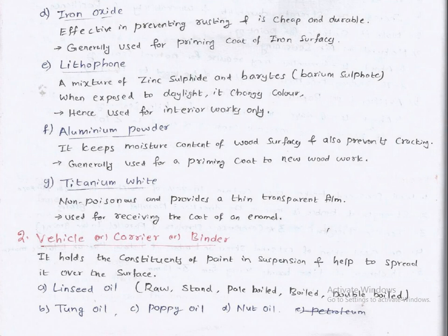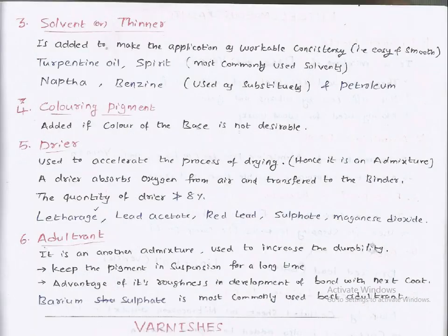Solvent or thinner. It is added to make the application workable, consistent, easy and smooth. Turpentine oil, spirit, most commonly used solvent. Naphtha, benzene, used as substitutes, and petroleum. Colored pigments, added if color of the base is not desirable.